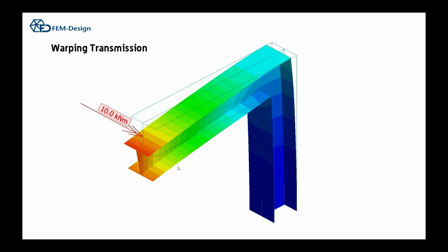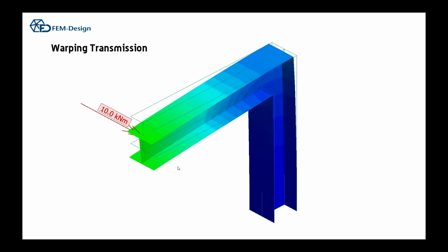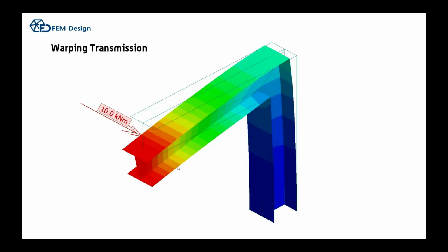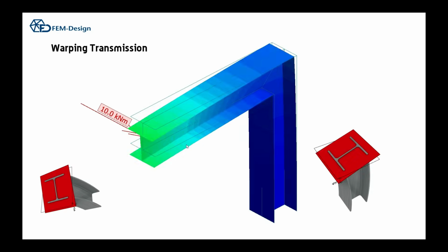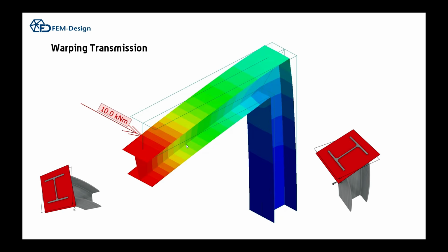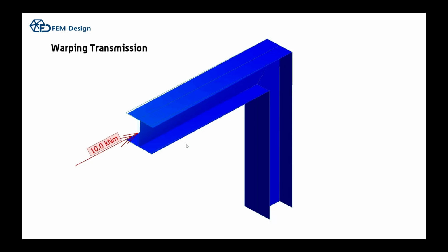With the classical beam degrees of freedom, we think of this as a vertical bending of the beam. How it transmits from beam to column is really clear, because the bending y of the column is also a bending about the strong axis of the column, so they are linked together. So we can automate the transmission.